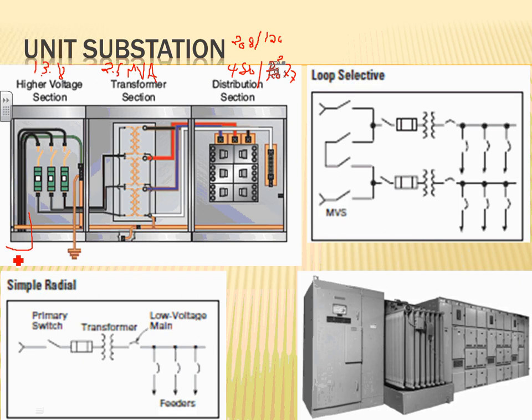So when you have a bigger riser, you can have a 13.8 feeder that goes all the way to the 15th or 16th floor, 36th floor, and from there, you take the voltage from 13.8 down to 480 and feed 1, 2, 3, 4 floors underneath it and so forth. That will be the best distribution system that you can design.